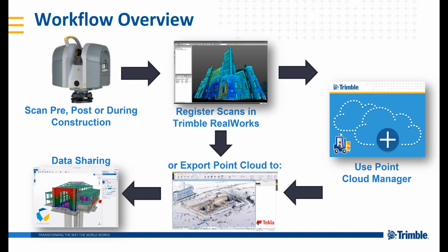So David has gone out and created scans of that Westminster project. He's registered them within RealWorks, and then he sent those files to me. And then there's one of two things that I can do with those. I can bring them directly into Tekla Structures and begin interacting with the point cloud in my model, or I can bring it into a program called the Point Cloud Manager, which is a free download available on the Tekla warehouse. That's a standalone point cloud viewer and allows you some real basic functionality as far as creating measurements within the point cloud and even just doing some real simple cropping of the point cloud.